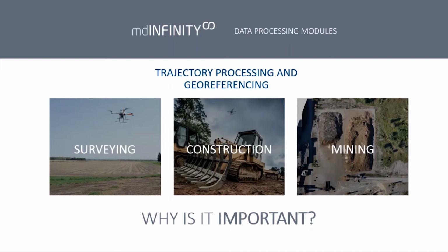The big benefit of what microdrones does is the streamlined workflow all through one suite of software, be it the cloud or the desktop version of mdInfinity. There's some big benefits that you can see. With surveying, things happen in the field. Sometimes, let's say, the wind picks up and knocks over your base station throughout the flight. The huge benefit of mdInfinity is you don't have to worry about that. If something happened to your base station, you can actually use some of the virtual base stations we have to offer, such as a PPRTX or SmartBase.